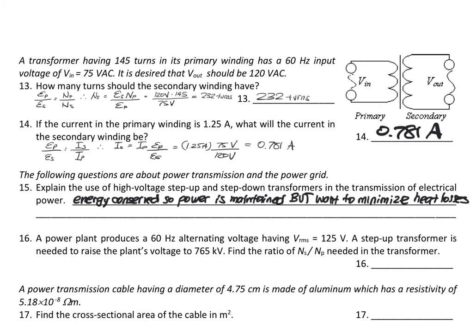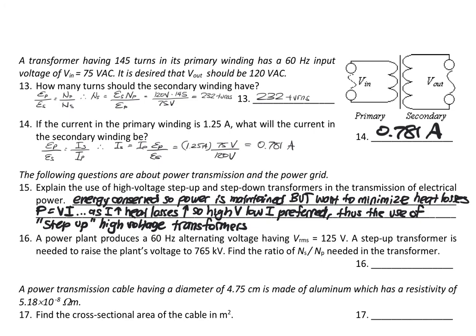That would be dumb. So in any case, let's remember that power is the product of voltage and current. And the more current we have, the more heat losses we have. So the amount of actual current, quote unquote, flowing through the wire, there's going to be greater heat losses. So in terms of the power, we want to have a large voltage and a smaller current, not a low voltage and a higher current. And so, yeah, you want high voltage and low current.